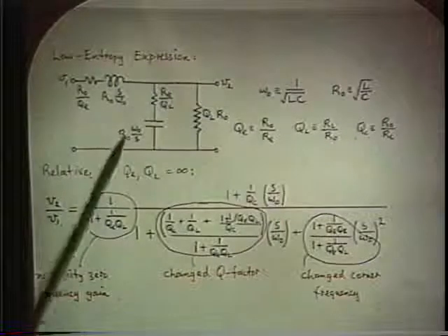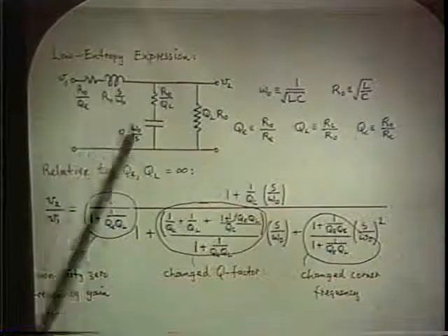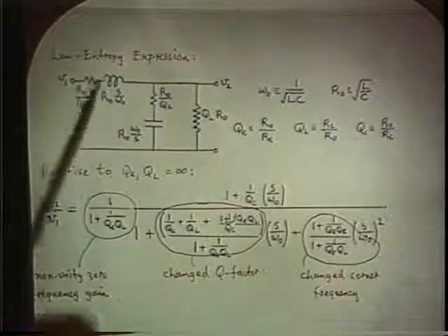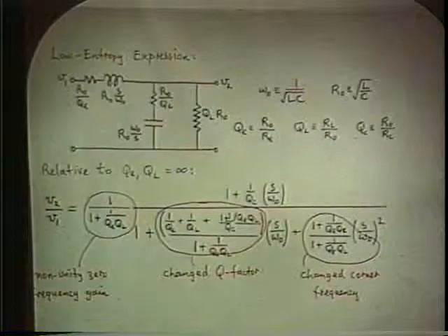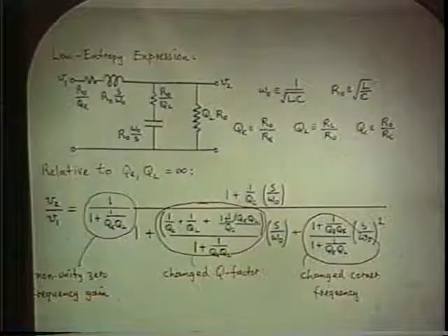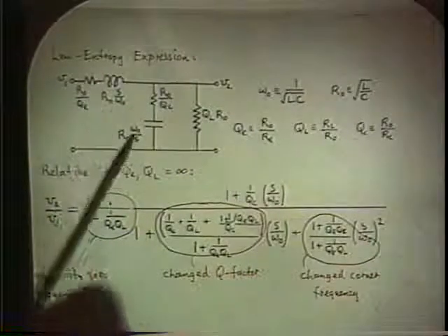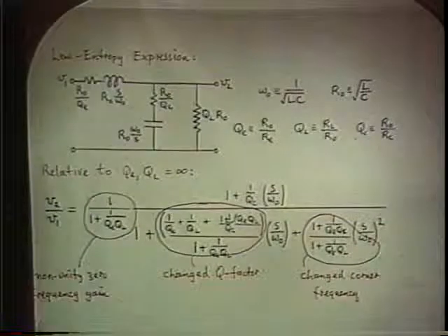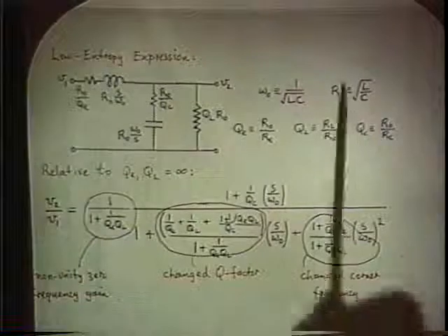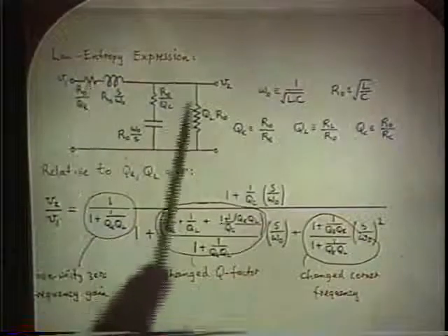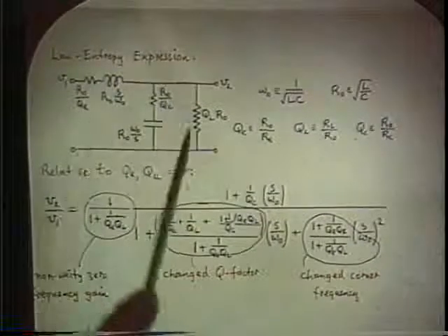And there's even one further step. You know that what you want in the answer is not L and C. You want the inductive reactance and the capacitive reactance. So you really want SL and 1 over SC. So introduce that as well. And when you invert those definitions, this is what the circuit reactances come out to be.